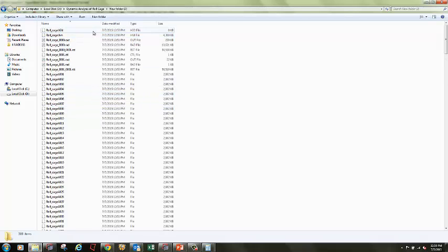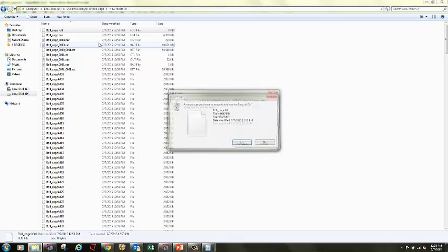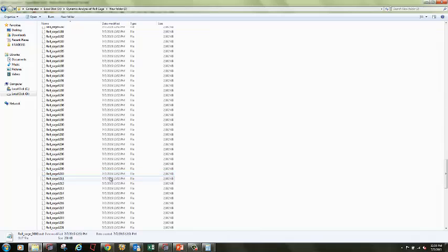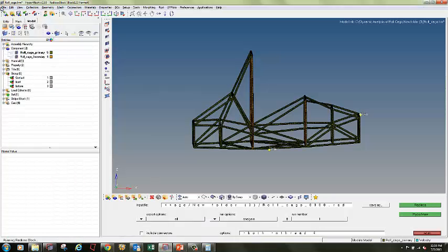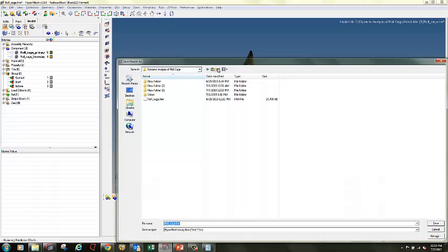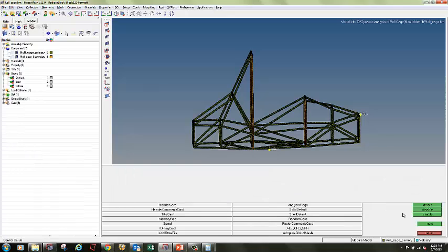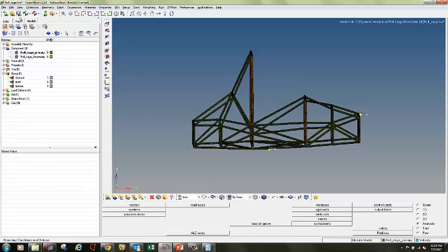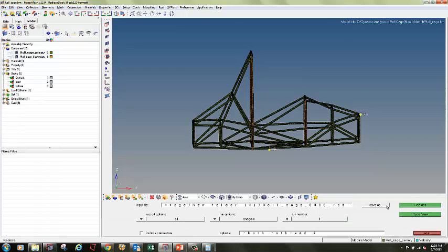So apart from the HM file, what I will do is save the file again in a new folder, and just change the value of engine animation dt to 0.00002. I have reduced it to one tenth. So I will save this file again and run the animation.